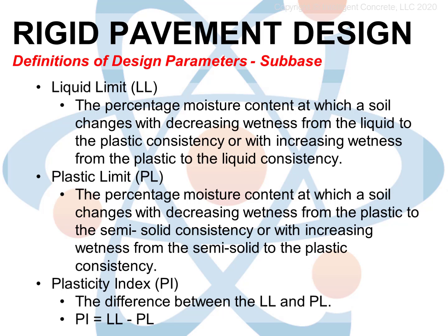The Atterberg limits are only performed on the silt and clay fraction of a soil, so the amount of sand when combined with the Atterberg limits tells an engineer if trouble might be brewing. In our case, because we have relatively low amounts of silt and clay, a higher PI, plasticity index, could be considered acceptable because there is a lot of sand present to carry the load. Sand, by definition, has no Atterberg limits, and it is what contributes the most to a soil's structural stability.